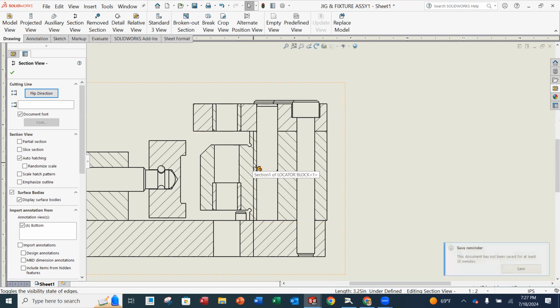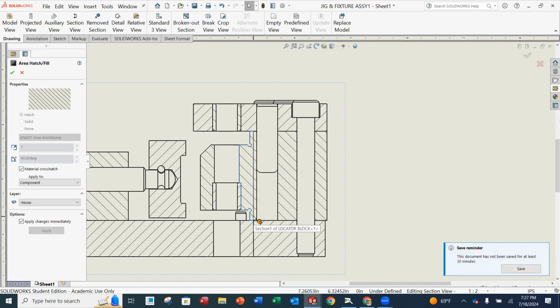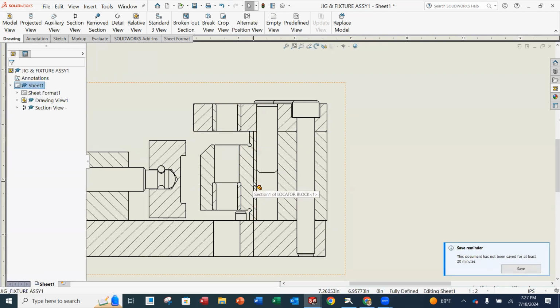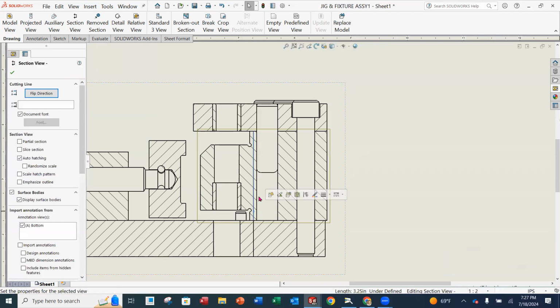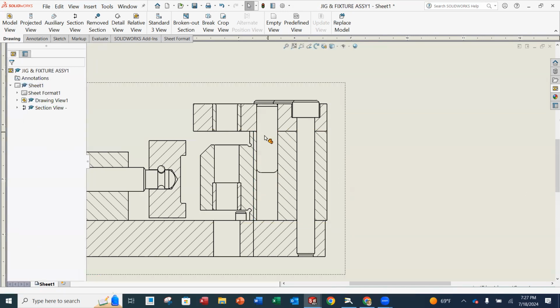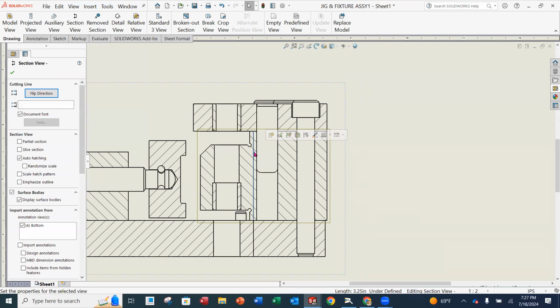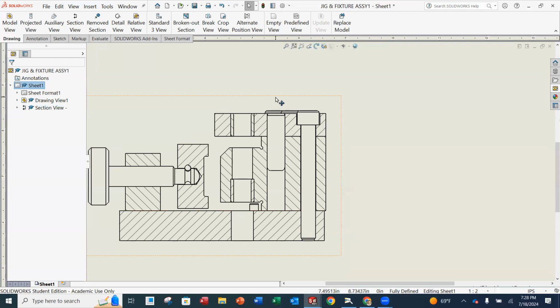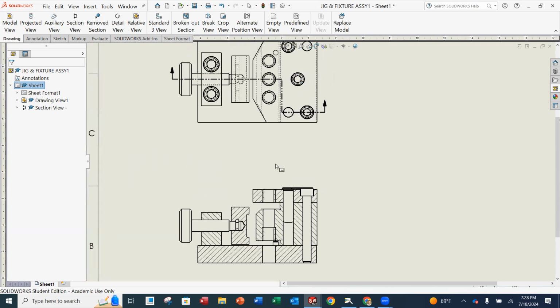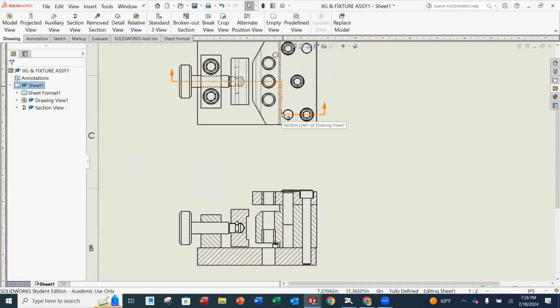There's 2 lines here, I believe. We have to click it. Oopsie. Click it again. And activate it. There it is. There we go. Activate it. I missed it. Let's try it again. There it is. Okay. And hide edge. If you move around too much, that dialog box goes away. Let's click it and hide edge. And now you should have no vertical lines here. You need to remove those. Again, it's because of the vertical line that we see here. That's that foreshortening that it does.